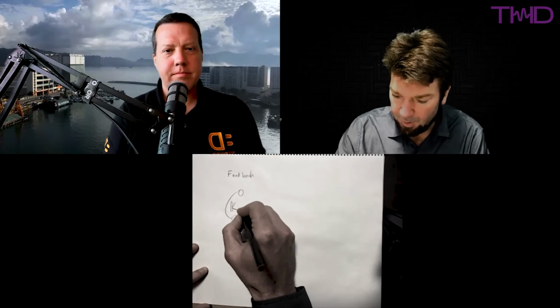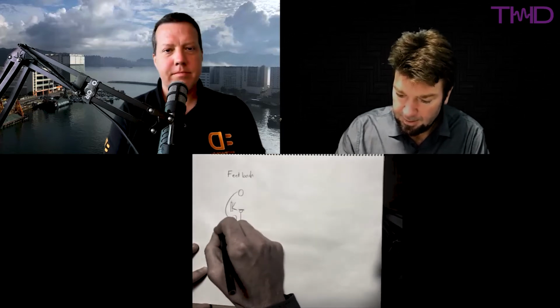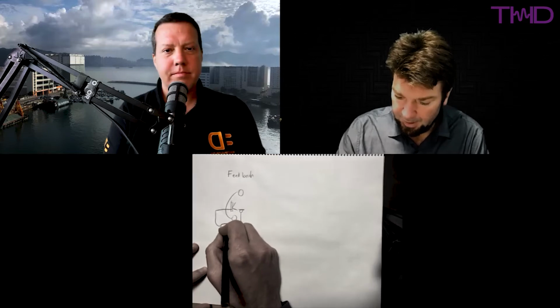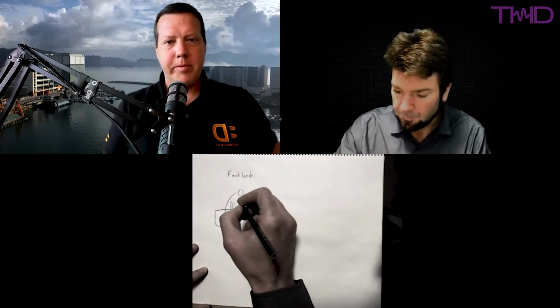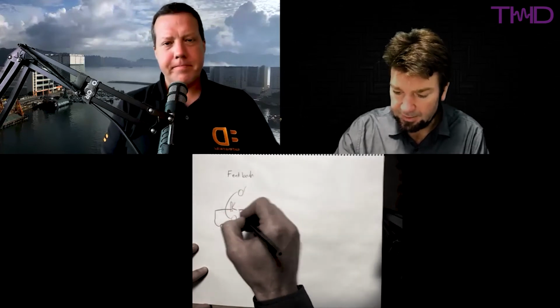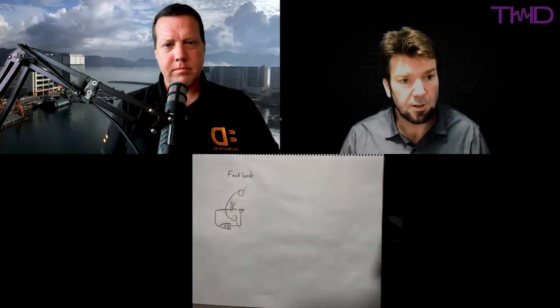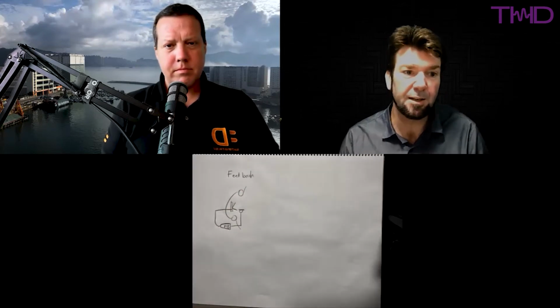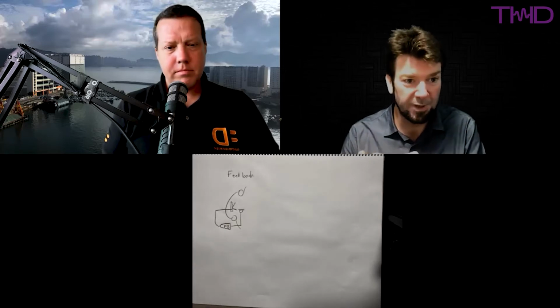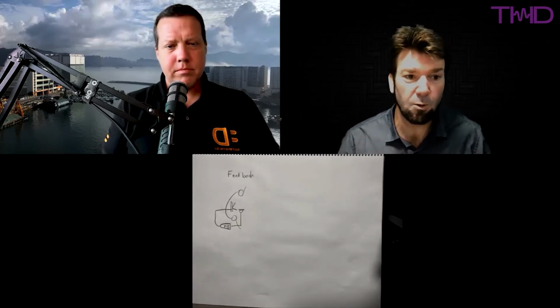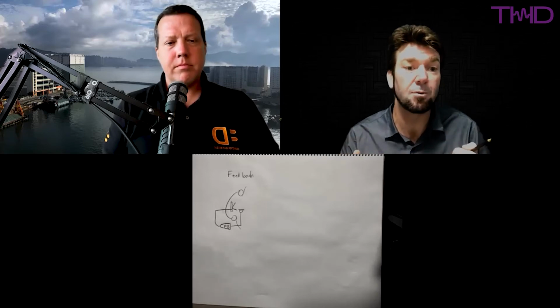But there's one concept that I'll talk about with feedback first, to highlight this. In the case of feedback, you have a speaker here inside the ear cup and a microphone, and that goes through some FB filter. Feedback filter. Yep. Okay. And so you have some sound energy inside this chamber, and you create a cancellation signal from the speaker. There's one concept that what you're doing effectively is pulling that energy out by moving the speaker diaphragm, and it's going out as heat into the coil. It's being transformed into electrical and heat energy in the speaker.